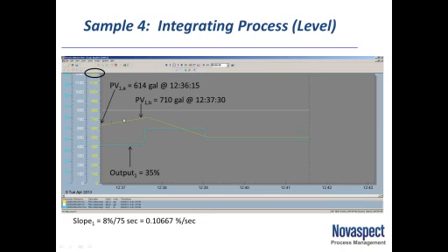The first thing was calculate the slope. Just measure the level here and its timestamp, the level here and its timestamp, convert to percent of scale, and you'll see we changed 8% in 75 seconds. The reason I use seconds as my units rather than minutes is because DeltaV's reset time is in terms of seconds. As before, I make a bump change in my output, but I don't come to a new steady state. As long as more is going out than is going in, I continue to decrease at a constant slope that won't change until my valve position changes.